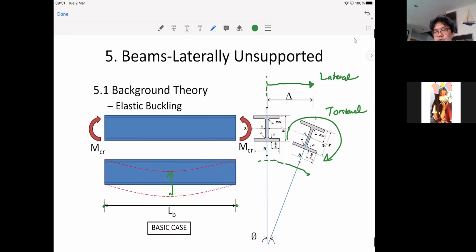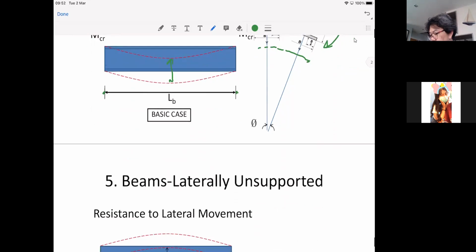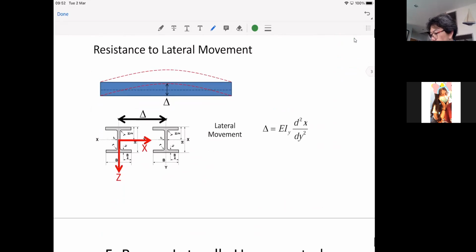Okay, so you see we have two kinds of displacement involved, rotation and displacement in the lateral direction. So that means in considering the flexural strength of the beam when it is laterally unsupported, you need to consider two qualities. That is the stiffness of the lateral movement, but I will not go into detail because if you really want to know how to develop the formula to approximate the behavior of the beam, that's very advanced stuff.